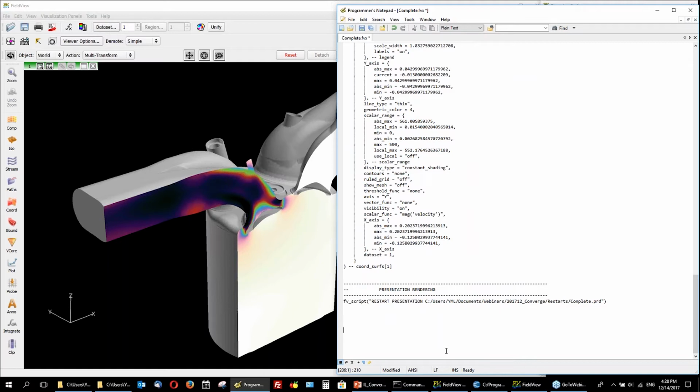So let's just say that I want to recreate the same session and automatically save an image at that step. So that's done with a very simple script command that's going to do print graphics. Then I pick the format, so we'll do PNG, for example, and I call it my picture. All right, so let's save that change.